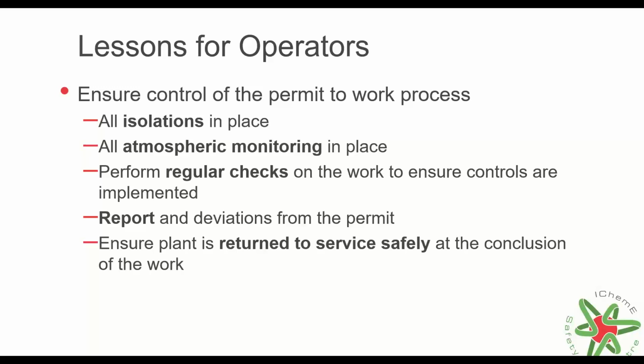The permit to work system is the only control we have to manage the introduction of that hot work activity into the space. And that is why the permit to work is just so important. The isolations that are required as part of it to make sure that we keep the flammable substances away as much as possible from the work that we're doing, that we monitor that atmosphere so that we know if our conditions or environment actually changes, and to make sure that the work remains within its scope.